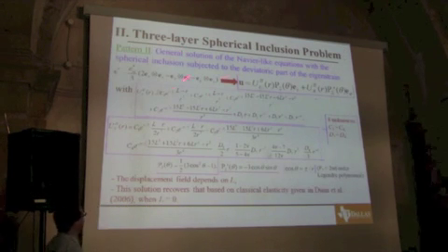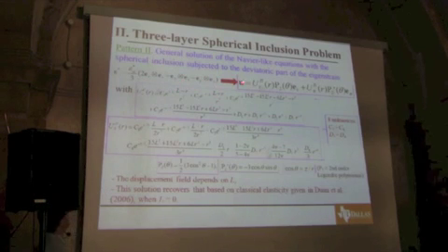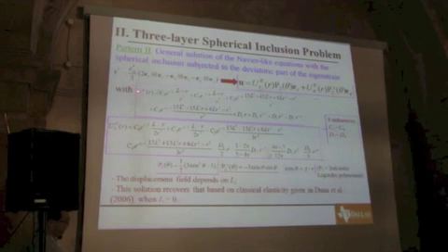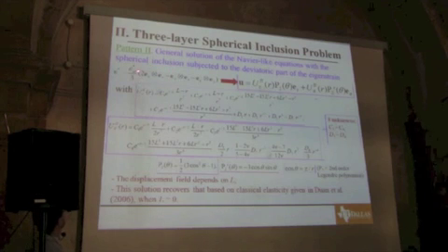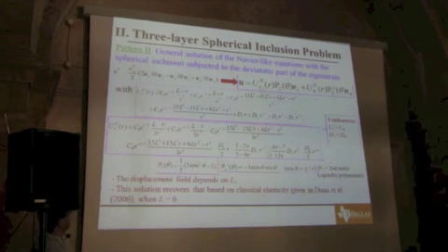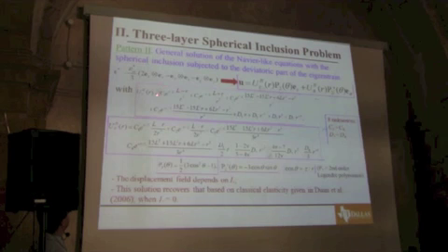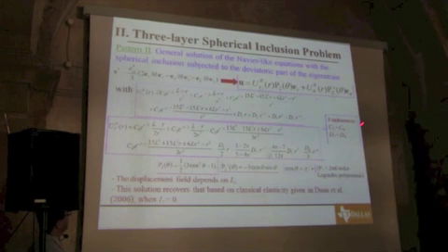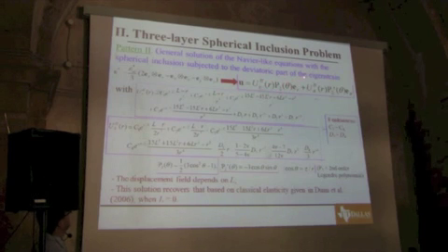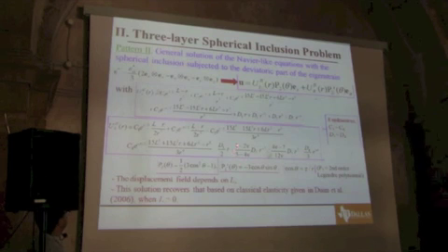Now for part 2, which is the first sub-problem for the uniaxial loading, we see the second part of the uniaxial loading is the deviatoric part. And the solution has this form. We were able to work it out. It took a lot of time. And it happened that we can have an analytical solution in closed form. There are 8 constants involved in these 2 expressions. They are coefficients of the radial component, the tangential component, and the Legendre polynomial. Once again we see the dependence on the material length scale parameter.